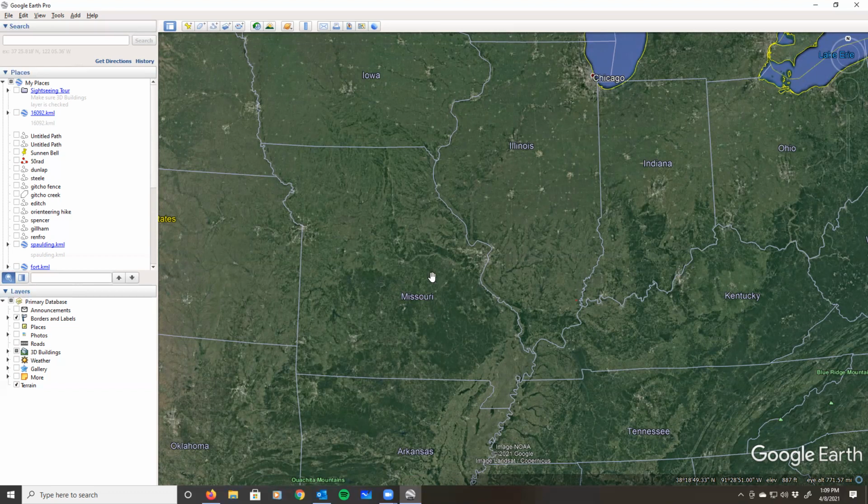What they do is, at the central meridian, it's sticking up above the plane of the projection. And so the distances that are measured there, it's basically the ground distance is longer, or the grid distance is shorter than the ground distance by 1 part in 17,000.